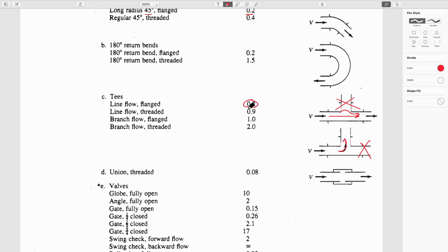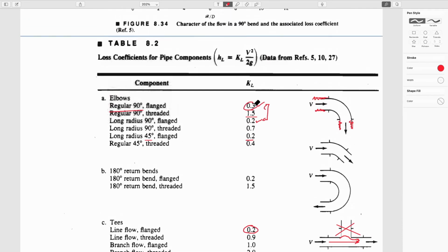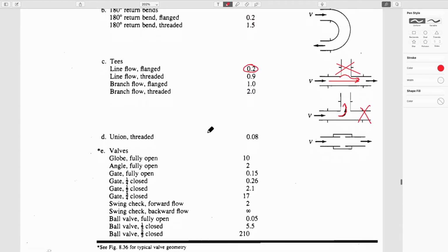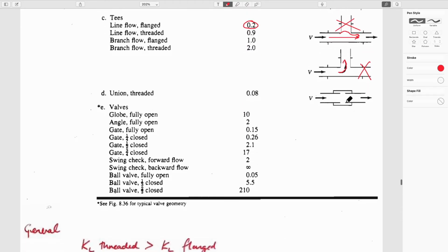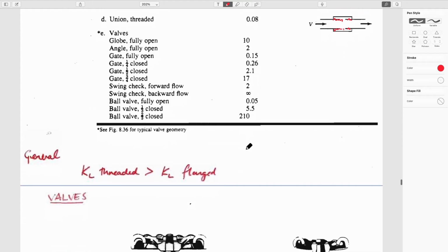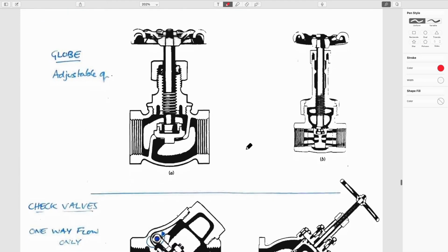And so this is 0.2 in this particular case, and I guess it was 0.3 here, and so you see something slightly different. And I guess you could even imagine it as the unions being threaded or so in plastic house pipes, I guess, PVC, they're put together, they're glued with a collar around it, so there is a little gap in the pipe here as it goes through here, and so you see some small amounts of loss coefficients as a result of those. And so you could imagine just using that as a tabulation to figure out what's going on.